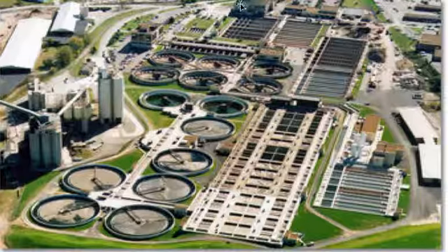From here, water comes into the plant, and after mechanical screening and manually separating all the solid material, the liquid will run out into all these lagoons one by one, and they have aerators like this one in order to maintain the BOD of all that lagoon for 24 hours. The water is running in each of these lagoons and is recycled day and night. And when it reaches the last lagoon, it will be free of all the toxic heavy metals.